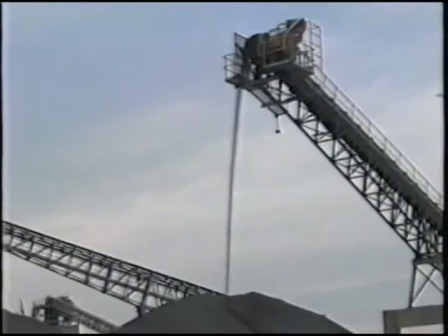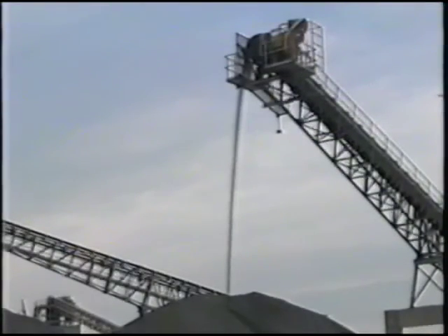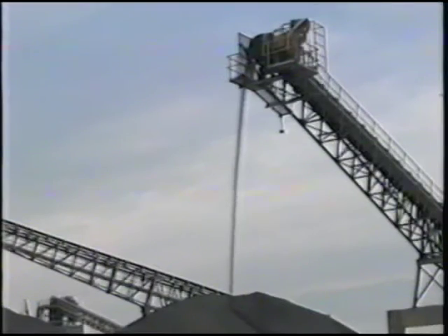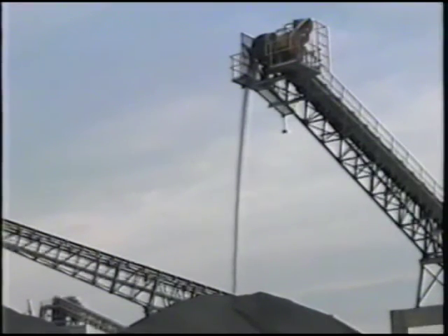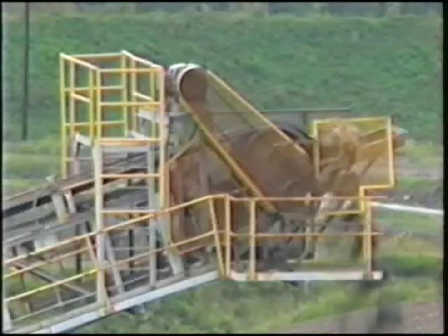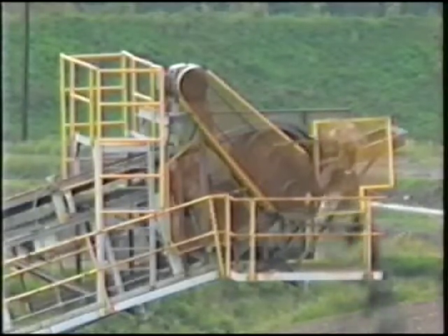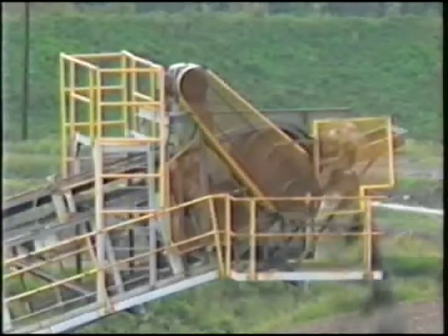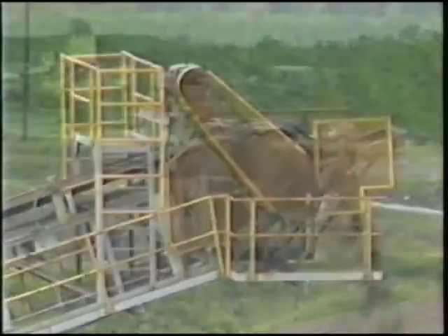The material from this conveyor is falling too far, segregating the material. The larger particles are rolling to the bottom of the pile. This conveyor is equipped with a device that minimizes segregation. The turning action of these plates blends the material as it comes off the conveyor. This limits the free fall of the larger particles.